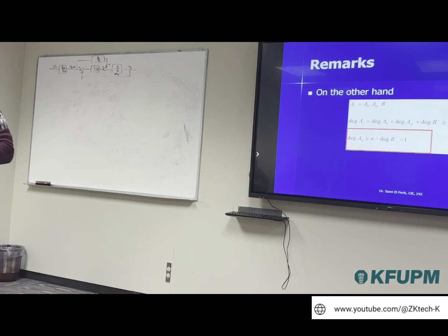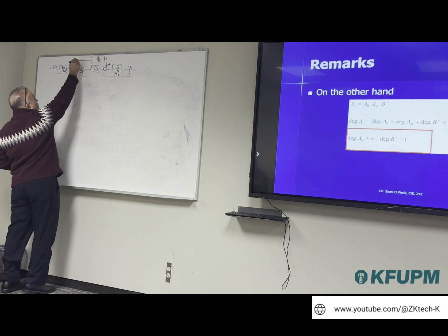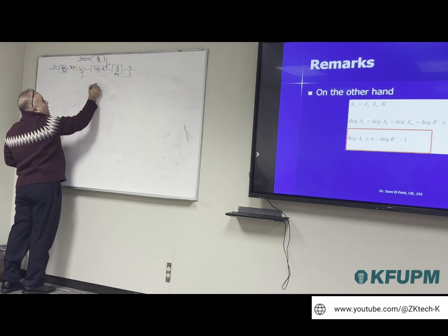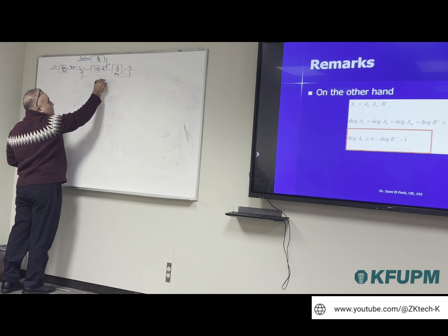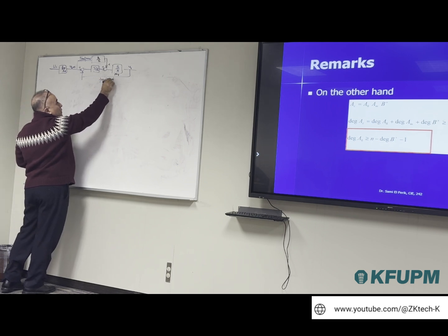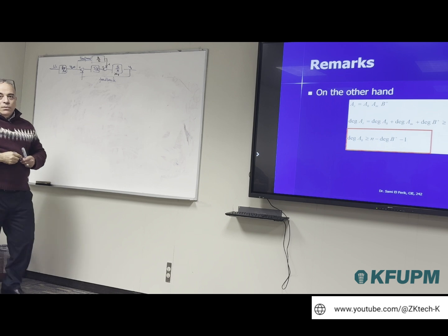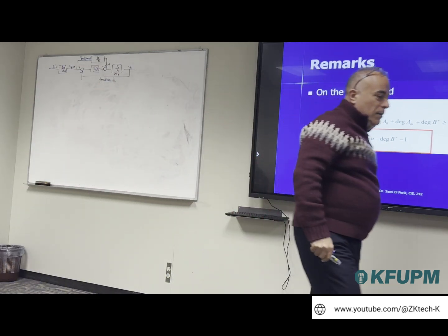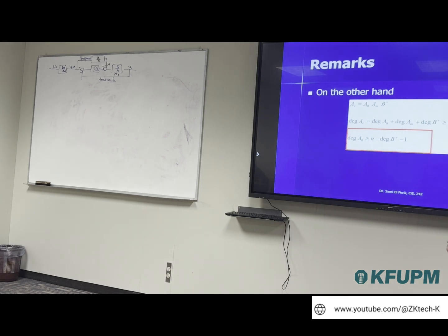So we have two components in the controller. We have a feed forward. And we have a feedback. So the feedback loop is supposed to correct this small difference that you have between Y and YM, where the difference is due to the fact that you don't know A and B correctly.